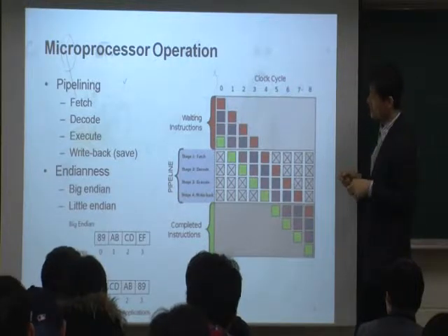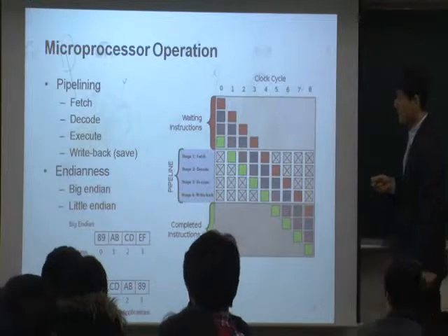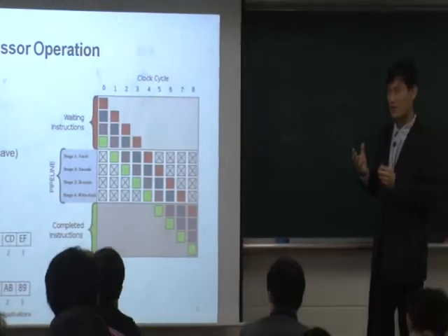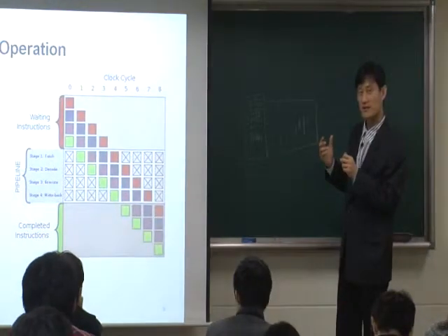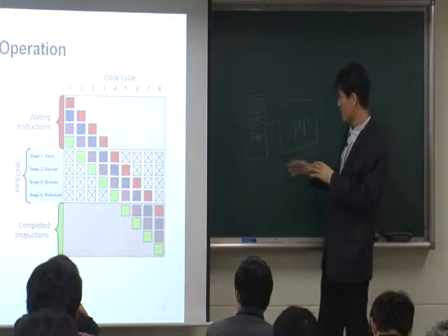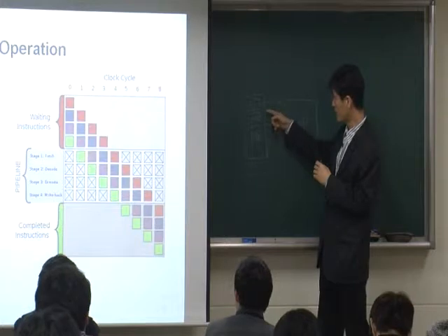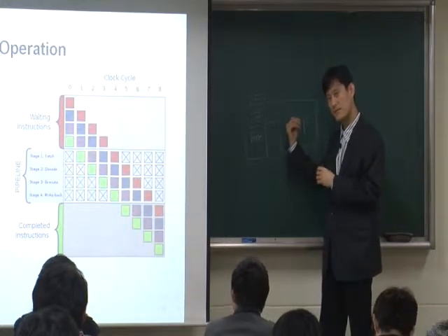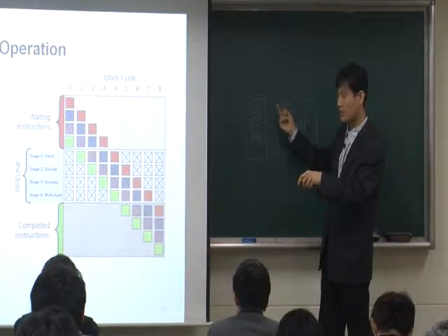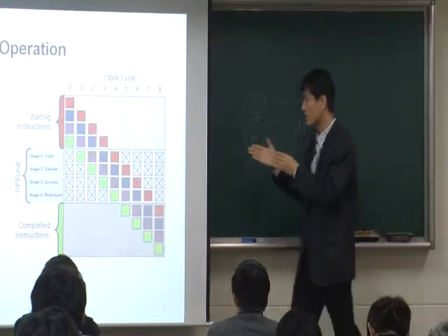Now, let's understand the pipelining. Since we have 4 different stages, what pipelining does is like the following. Microprocessor go there and fetch the first instruction, okay? And then next thing to do is a decode, right? So this microprocessor fetch it first, and on the next stage, look at this picture.